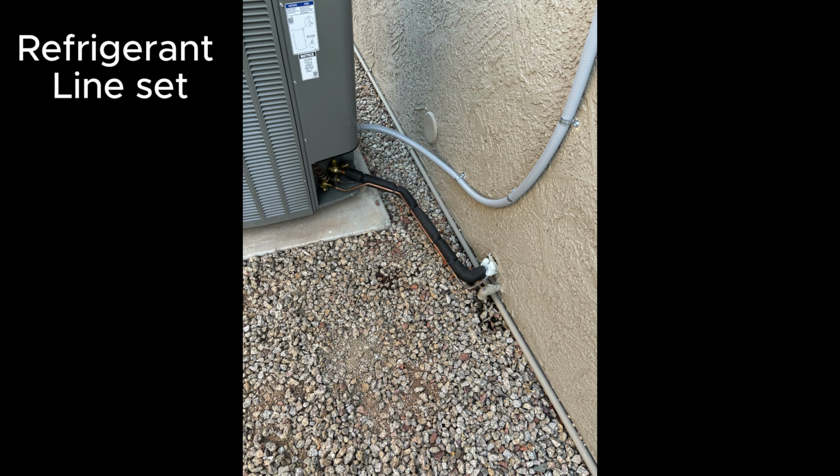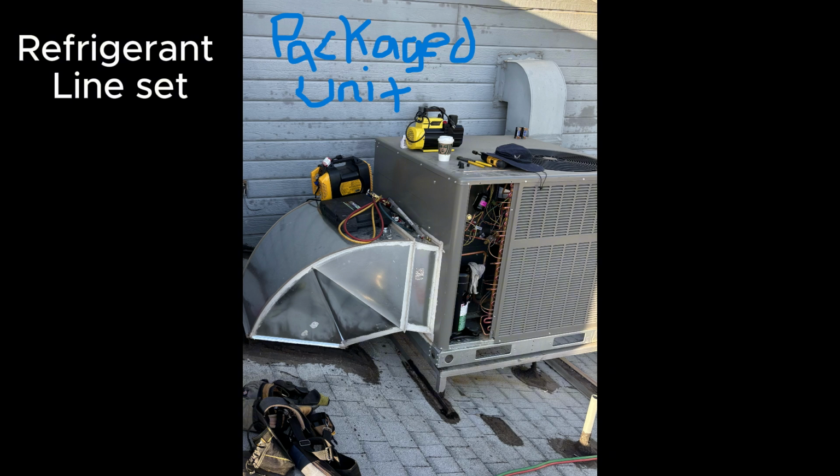So just be aware that especially if you have a split system, there's copper tubes called a line set, two of them specifically, a suction line and a liquid line, that travel from outside through your walls up into your attic or into your closet. It connects the two units, and that's why it's one system, even though it's split between the outdoor portion and the indoor portion. And again, if you have a packaged unit, the line set is extremely small and confined to the one box that everything is in.